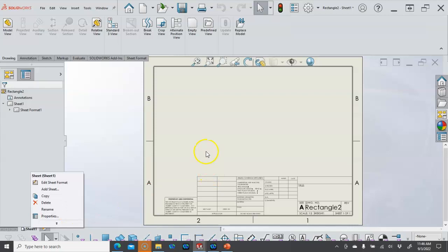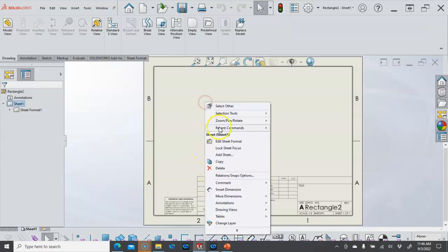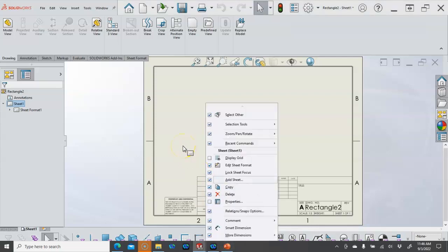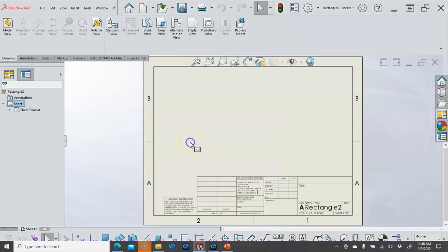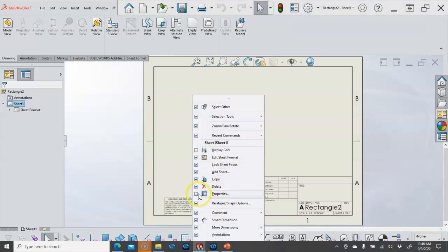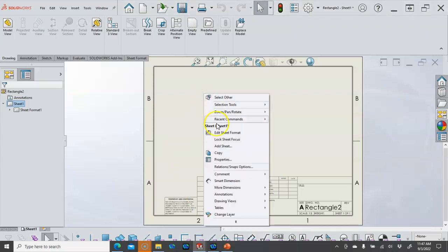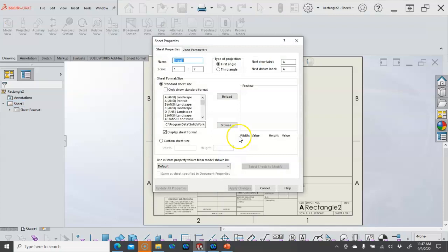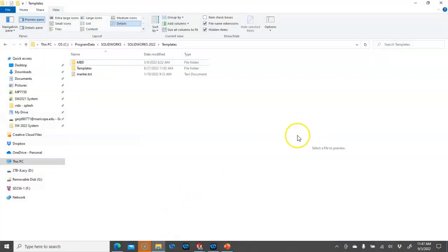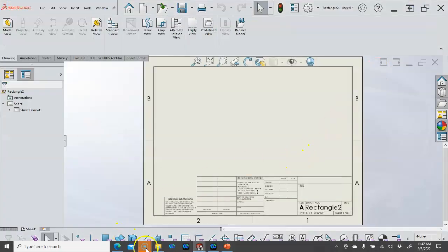All right, but here's one of those customized, and we'll revisit that again because I really want it to be there. So escape real quick. Oh, let's just click. Get a little bit higher up there. Customize menu. And I want to see properties, but I don't really want to delete, so I can turn those off, and then that modifies the menu to where I'll have the properties. I can go into third angle projection, apply the changes, and we'll get out of that, maybe.